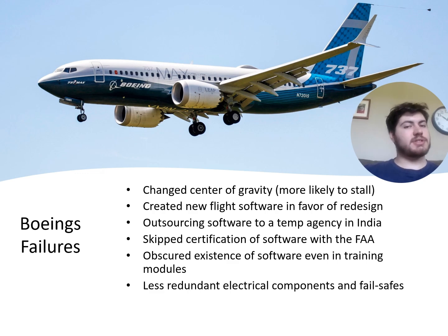The new 737 MAX was created to replace its 707 and 727 predecessors, with some major design changes added. Boeing changed the center of gravity and lift compared to Boeing's previous installments in favor of minimizing the trim drag effect and optimizing efficiency, neglectfully ignoring how it increased the plane's chances to stall.